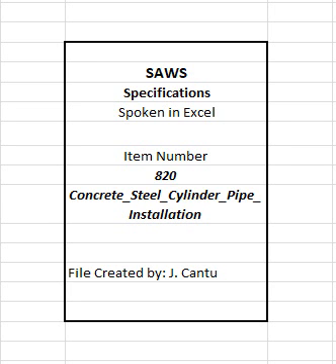4. The measurement of each line of pipe of each size will be continuous and shall include the full laying lengths of all fittings and valves installed between the ends of such line, except that the laying length of reducers will be divided equally between the connected pipe sizes. 5. Lines leading to a tapping connection with an existing main will be measured to the center of the tapped main.